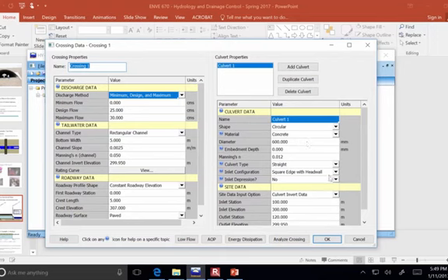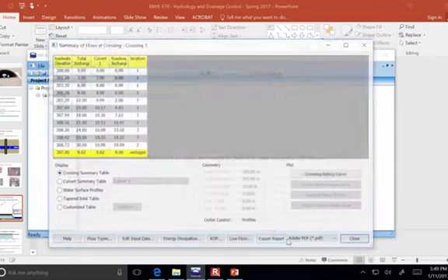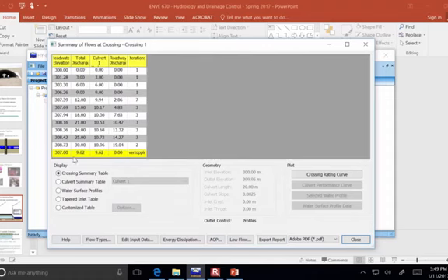How big would it have to be? Maybe we could put in more barrels. You know, could we put in 5 barrels? What's going to happen there? Analyze it again. So with 5 barrels, things are improved. At 25 cubic meters per second, now we've got 10 cubic meters per second through the pipes and 14 going over the road. So that's less of the flow in the wrong place, but still not good enough.